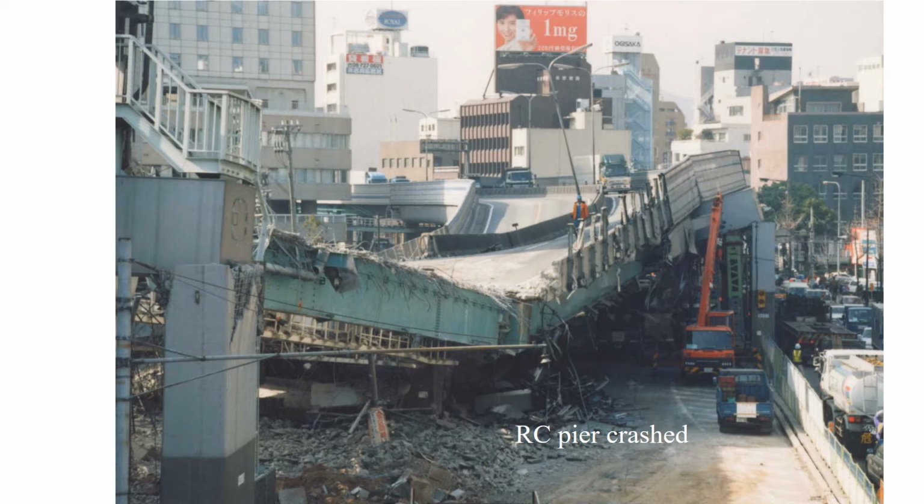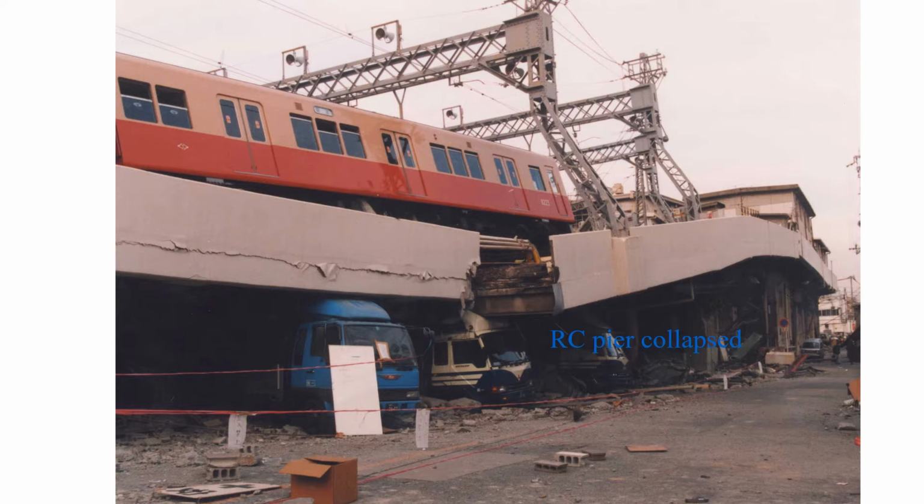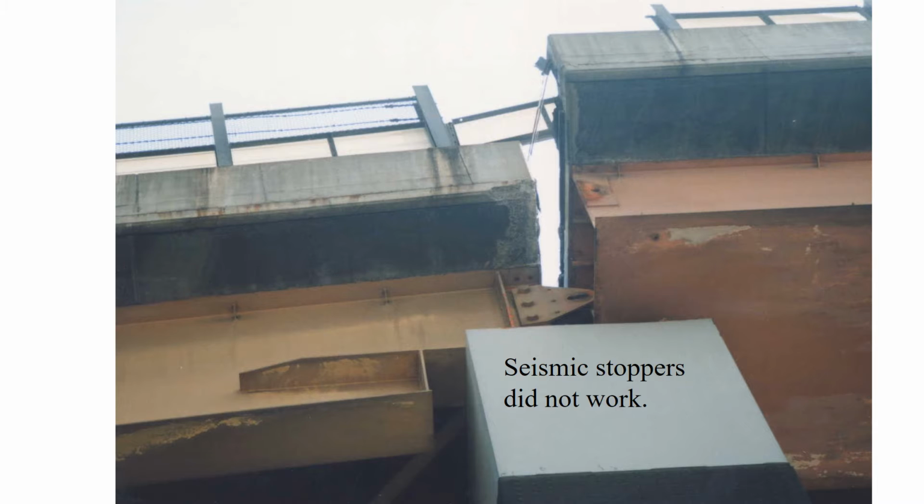This continuous plate girder bridge collapsed when the RC pier crashed at the intermediate supports. This is a railway bridge. RC pier broke, which collapsed the girder. Adjacent girders are connected by the seismic stoppers to prevent the girder falling down. However, the seismic stopper did not work on many bridges.